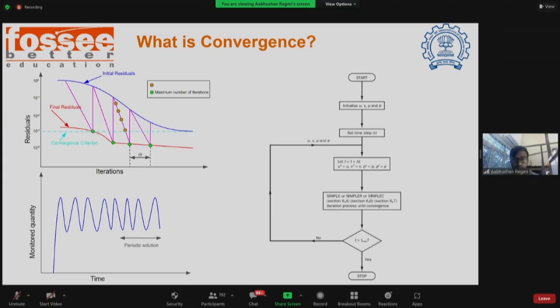In the boundary condition files for u and p, there was an internalField line, if we remember, and that is our initial condition. Initially all the variables in our domain will be initialized to that value. I think you remember it was internalField uniform (0 0 0) for velocity, and for pressure it would be only 0 because pressure is a scalar.